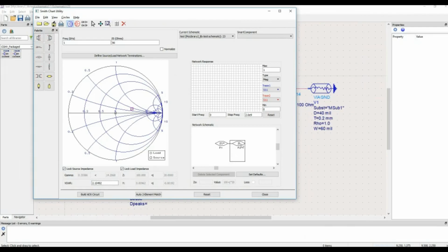So I have selected this ZL and now I need to have a capacitive or inductive element to reach 1. So here are these elements in the palette again. You can use inductive elements, you can use capacitive elements, you can use transmission lines in any reactive configuration so that you reach this particular source impedance. For example, I am interested in using a transmission line. So I have selected this transmission line. This is a series transmission line, not any stub.